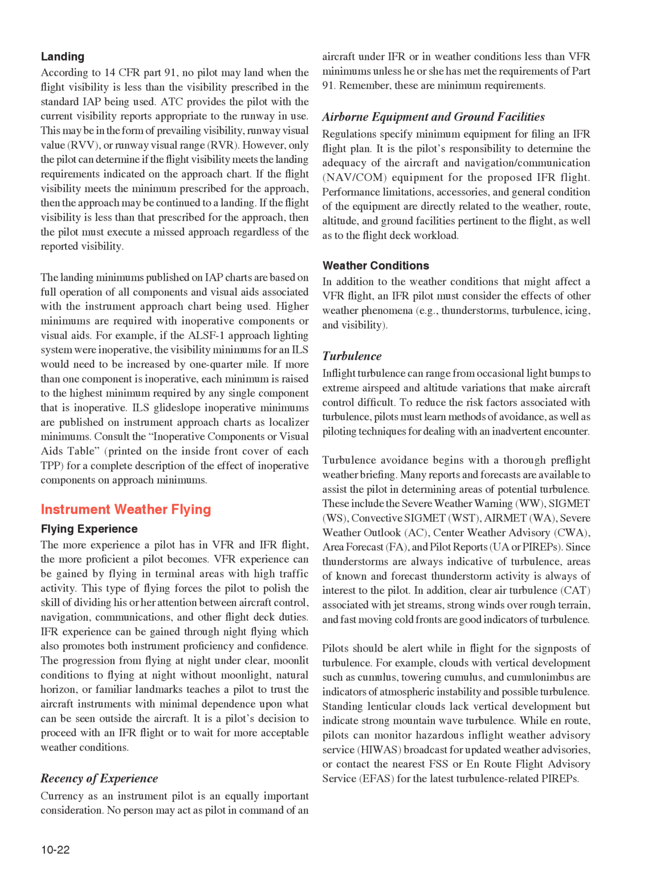IFR experience can be gained through night flying, which also promotes both instrument proficiency and confidence. The progression from flying at night under clear, moonlit conditions to flying at night without moonlight, natural horizon, or familiar landmarks teaches a pilot to trust the aircraft instruments with minimal dependence upon what can be seen outside the aircraft. It is a pilot's decision to proceed with an IFR flight or to wait for more acceptable weather conditions.